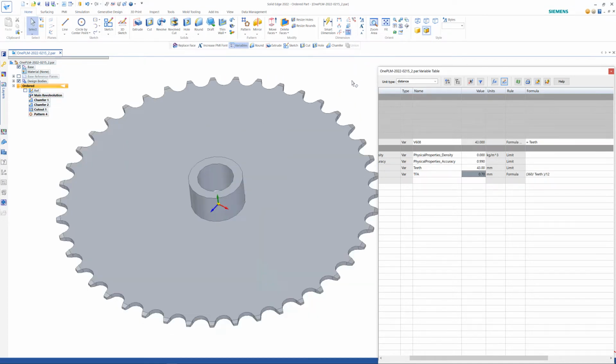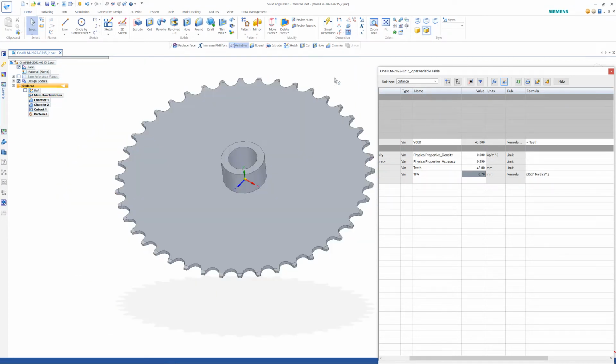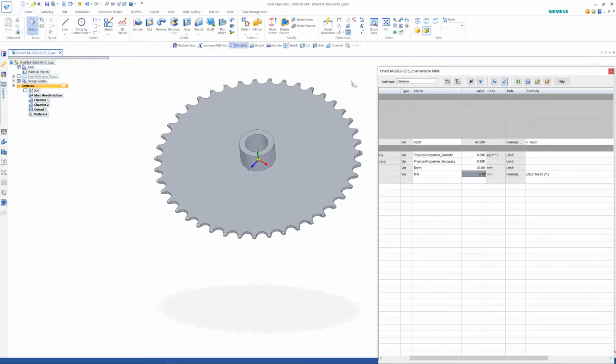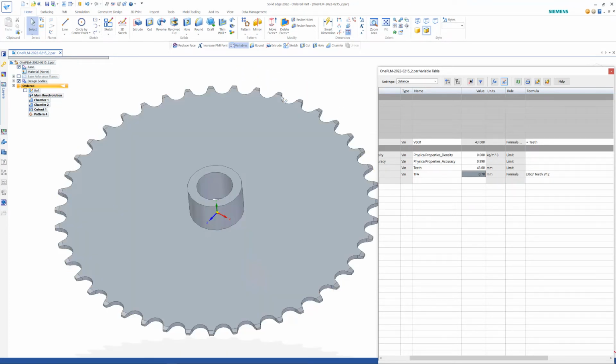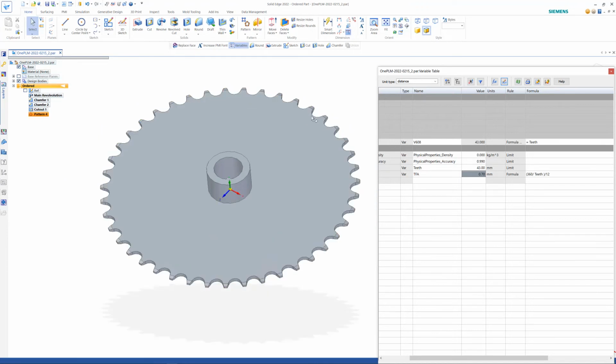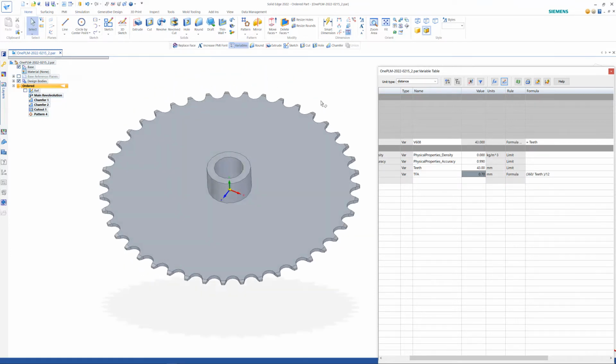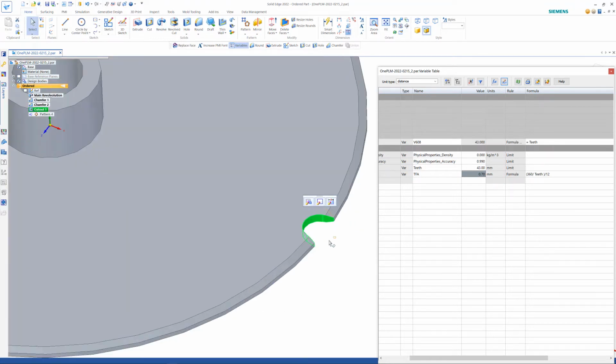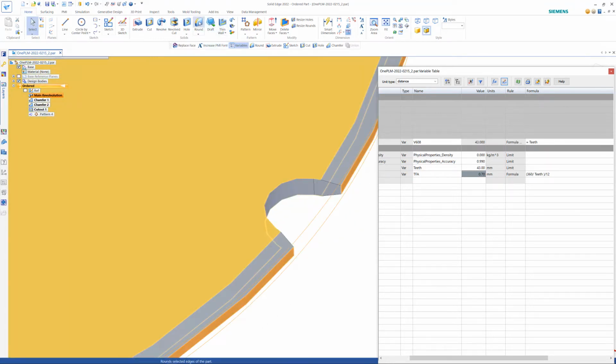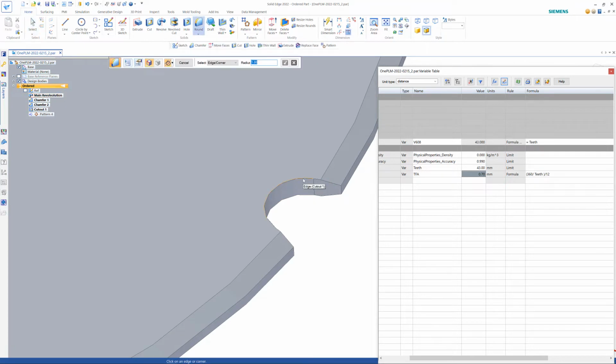Okay, so next section we're going to have a look at creating some lightweight cutouts on these. Worth noting, sometimes some people might want to put rounds on there. Just be aware, as soon as you put a round on those edges, you are going to really slow it down. So think about suppressing that if you are going to create a round on there. So if I do an F4 on there, and then add a round to that feature, for instance. Let's just see if that will do it to the entire feature. Let's go 0.4.